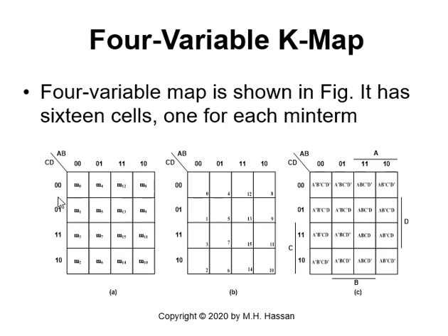I have also here 0, 0, 0, 1, 1, 1, 1, 0. And the location of the minterms as shown will be 0, 1, then we jump a row, 2, 3, 4, 5, 6, and 7. Then we jump a column, we'll have 8, 9, 10, 11. Then we go back to this column, 12, 13, 14, 15. So this is the minterm A, B, C, D, and those are filled out here.